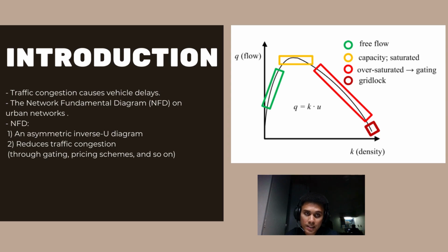As a result of this data, the traffic controller will seek to keep the network from being oversupplied while still serving traffic at the required level. To achieve maximum flow, the network should be operated at or below critical occupancy accumulation. This goal is achievable with good traffic management.